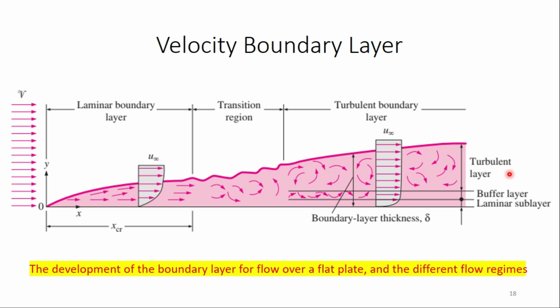are very dominant. The intense mixing of the fluid in the turbulent flow as a result of rapid fluctuations enhances the heat and the momentum transfer between the fluid particles, which increases the friction force on the surface and the convection heat transfer rate. It also causes the boundary layer to enlarge as the fluid moves in the right direction. Both the friction and the heat transfer coefficients reach maximum values when the flow becomes fully turbulent. So it will come as no surprise that a special effort is made in the design of the heat transfer coefficient associated with the turbulent flow. The enhancement in the heat transfer in the turbulent flow does not come for free.